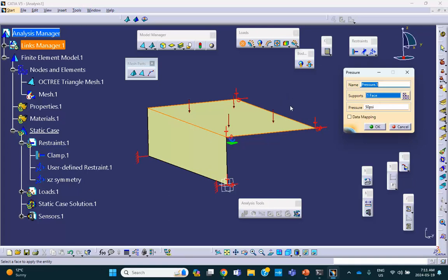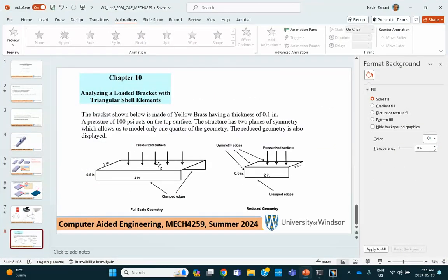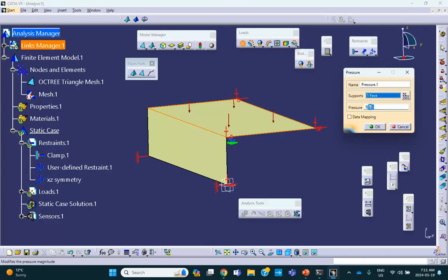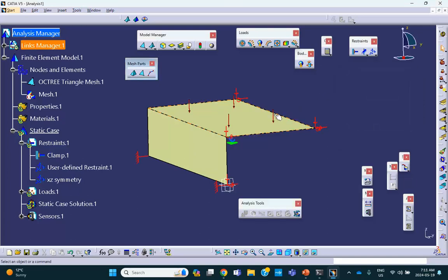If I was applying a load of 1,000 pounds here, then on that piece you get 1/4 of it, so it's going to be 250. But pressure stays as it is. 100. You say okay. Incidentally, if this is to be upward, then make it minus 100. In other words, if you apply the pressure from the bottom so it pushes out, you put a minus on.